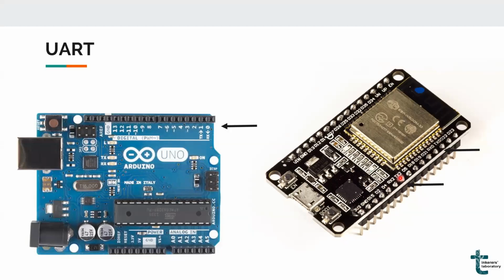And as I mentioned earlier, all of the pins of the ESP32 are not exposed on all development boards. So this board that we have has only 30 pins. It didn't have these pins exposed, the RX1 and the TX1. So those pins are not exposed in this development board.